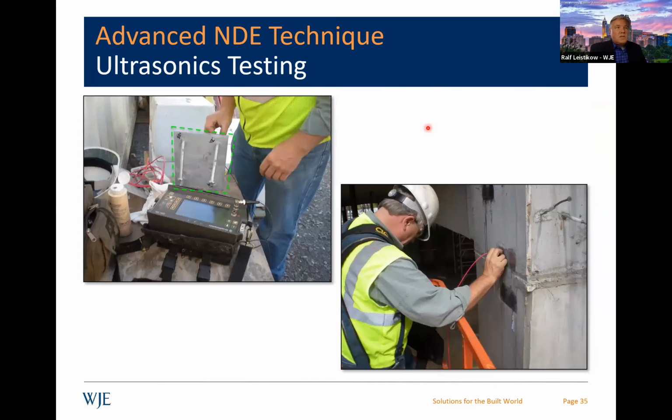I wanted to show you this example. This was a project I worked on where we got a call on a parking deck that had precast panels that were supposed to be attached to these columns. There was concern, apparently, that when the rebar was placed, some of the ties were in the way of the plate, and somebody decided to bend the studs.